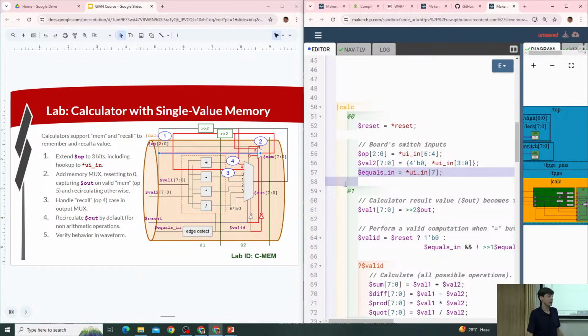Yeah, same deal. When you power on, the power has to stabilize. After the power is stabilized, you hold reset for some minimal number of cycles, you deassert reset. So again, you want to create that synchronous reset and use that synchronous reset everywhere.